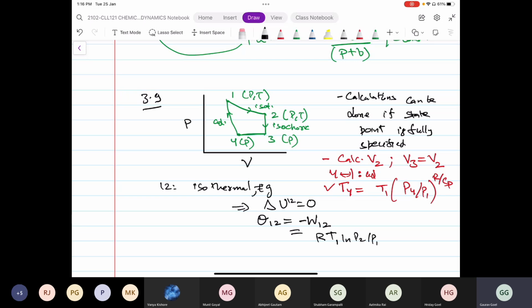As long as these are reversible, you can complete it. We'll discuss in chapters 5, 6, 7 how to complete the calculations when processes deviate from reversibility, which is pretty much always the case. But for now, if you assume reversible process, you can easily complete the calculation. So the key thing was to get the missing information. Once you do that, one more thing which might come in handy is that for a cyclic process, internal energy change is 0. That might come in handy for calculating one of the Qs or Ws. Any questions on this?